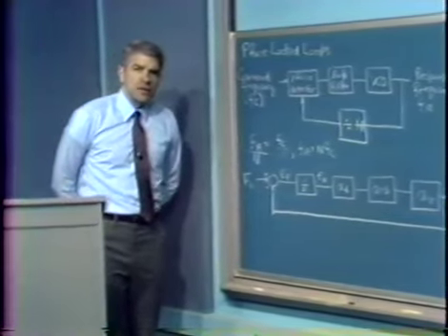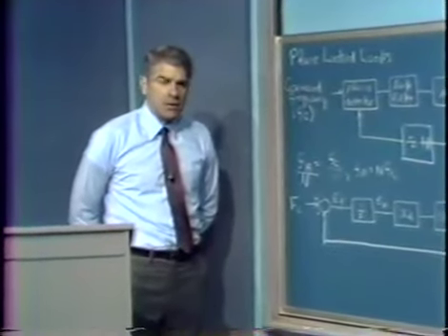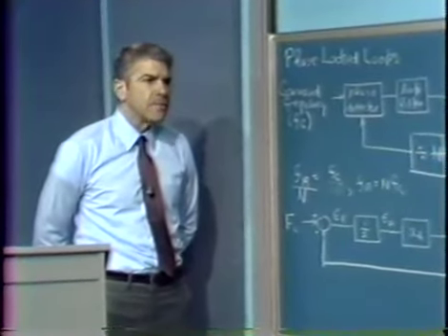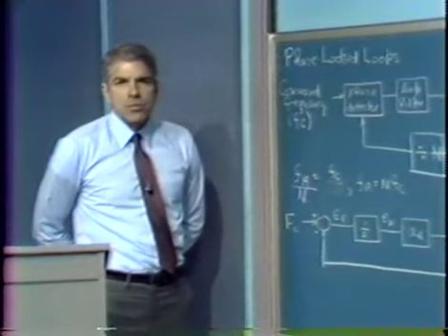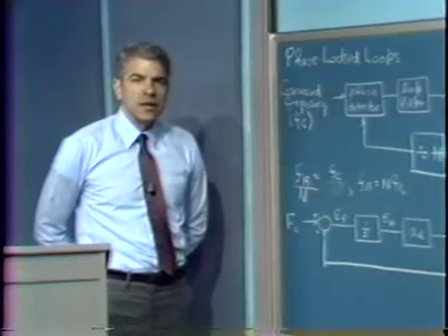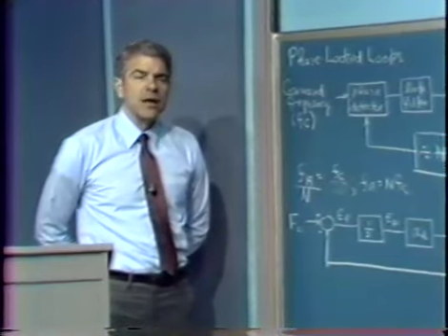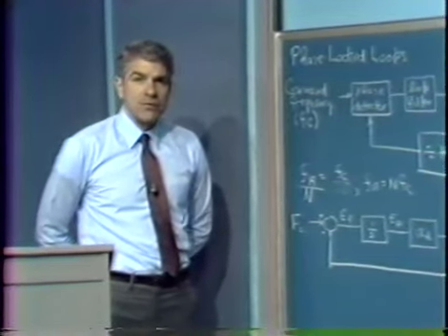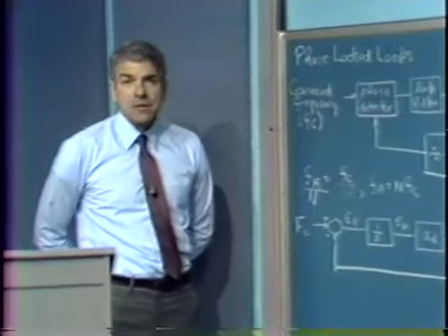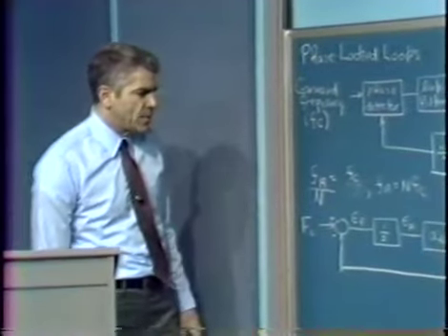In order to investigate the feedback aspects of a phase-locked loop, we have to look at a model for that sort of system, and in particular, we have to consider how we model the phase detector. As we'll see, these systems are typically nonlinear in quite important ways, and in ways that have very profound implications for the operation of a system. But generally, we can model them for some limited range of difference between the input frequency and the response frequency as a linear system.